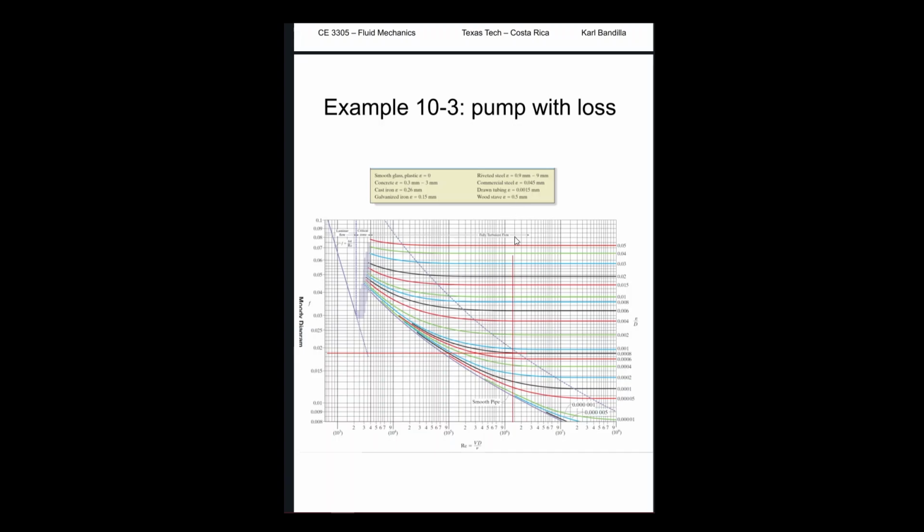Now, knowing these two, we can go into the Moody diagram, which we have down here. So we can look up our Reynolds number right here, 1.4 times 10 to the 6 would be this line right here. I already put the lines in. And then we can look up here, 0.0008 is this black line, so we just have to see where those two intersect.